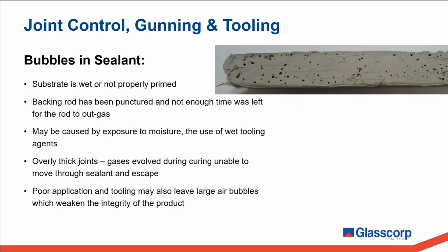Other potential factors, as I mentioned, wet tooling agents can contribute to this effect. Joints that are set overly thick may not allow for gases in the cavity to escape. And poor or insufficient tooling may result in bubbles being left in the sealant joint.